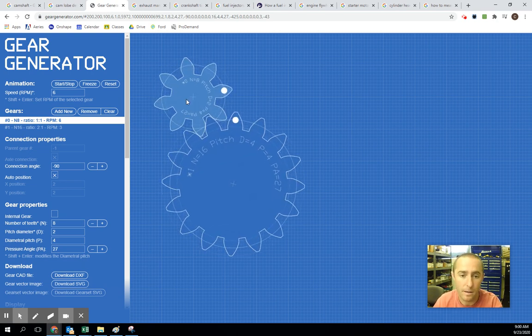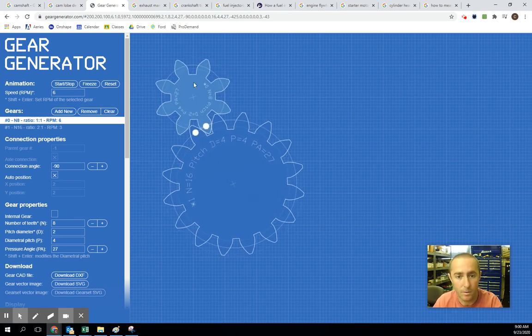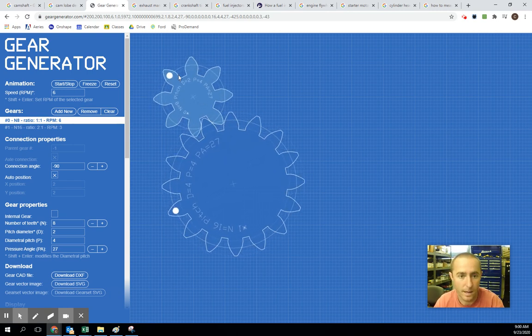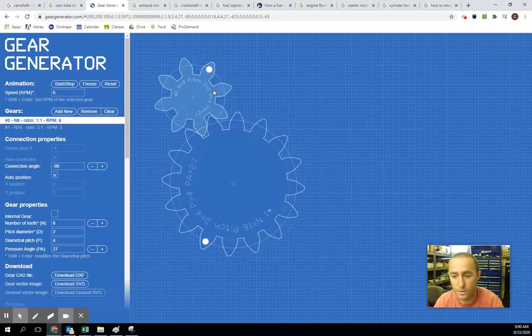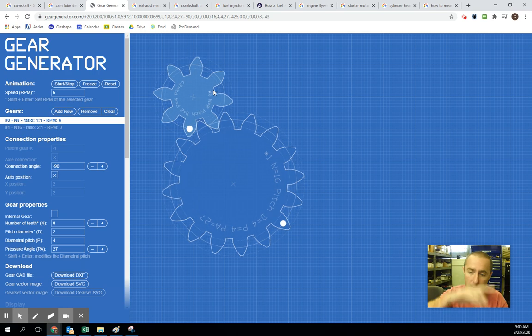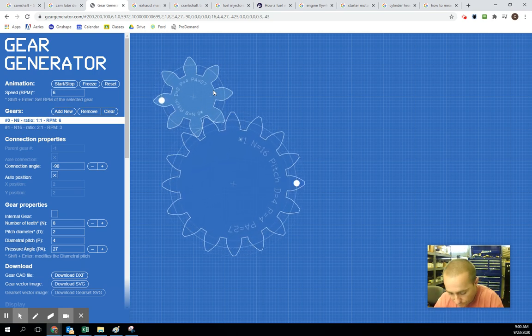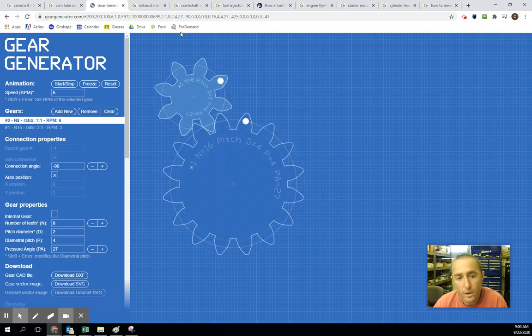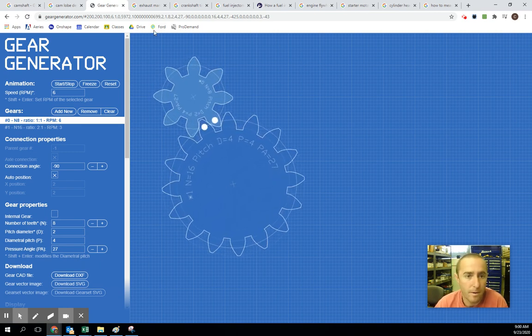And I did misspeak, I apologize. This doesn't rotate 4 times for 4 strokes. It's 2 times for 4 strokes, being all the way up as 1 stroke, all the way down as a second stroke. That would be 1 complete rotation. So just know that ratio, 2-to-1, every vehicle. That's the main part of that.